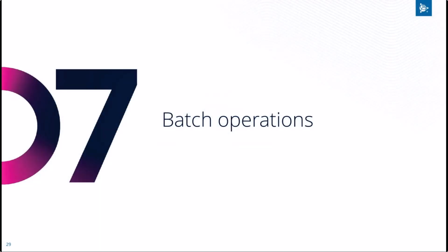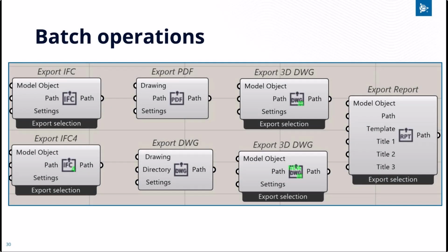And then what I said about the batch operations, which I really like because I believe that on every project you need to deliver something at the end. The Tekla model is not enough. And maybe you're using the Beam Publisher. That's great, this is a great tool. But with the drawing link, you can also do some things like those presented here. So the IFC, the older one, and also the 4.1, PDF, 3D, DWG.